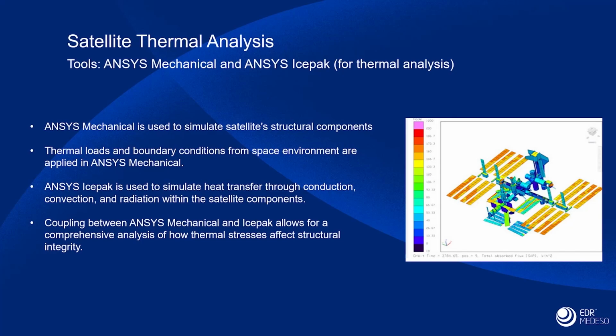And what we want to do is predict how these thermal and heat loads will affect the structural performance. So ranging from what you might consider a straightforward differential expansion problem right through to utilizing things like the latent heat capabilities of wax solidification to provide cooling in heat pipe systems. And I mention that because it was done quite recently on the James Webb Telescope, so I have some level of knowledge of that. Now, in addition, you'll see I've mentioned Icepak here.